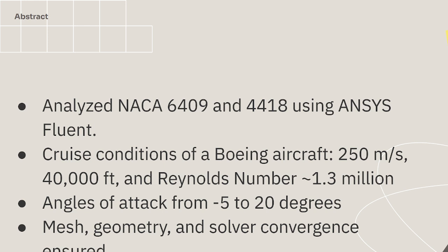In this study, I used Ansys Fluent to simulate the performance of the NACA 6409 and the NACA 4418 airfoils. The simulation model's cruise conditions are 250 meters per second of air inlet at 40,000 feet, with a Reynolds number of approximately 1.3 million. I varied the angle of attack from -5 to 20 degrees and focused on measuring lift and drag forces. Through mesh refinement, geometry checks, and solver convergence, I ensured reliable results. Ultimately, the NACA 6409 proved to be more efficient, producing higher lift with lower drag.